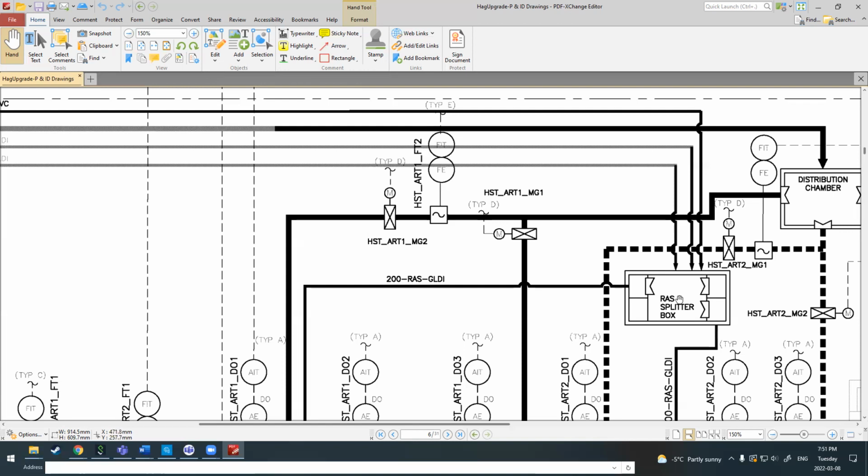So that in theory, as the level comes up, it's going to evenly flow out all of these weirs, unless you want to adjust. The weirs would be slightly adjustable, where you could pull the weir on one side up a couple of centimeters to force flow to the other side more than another. Does that make sense?